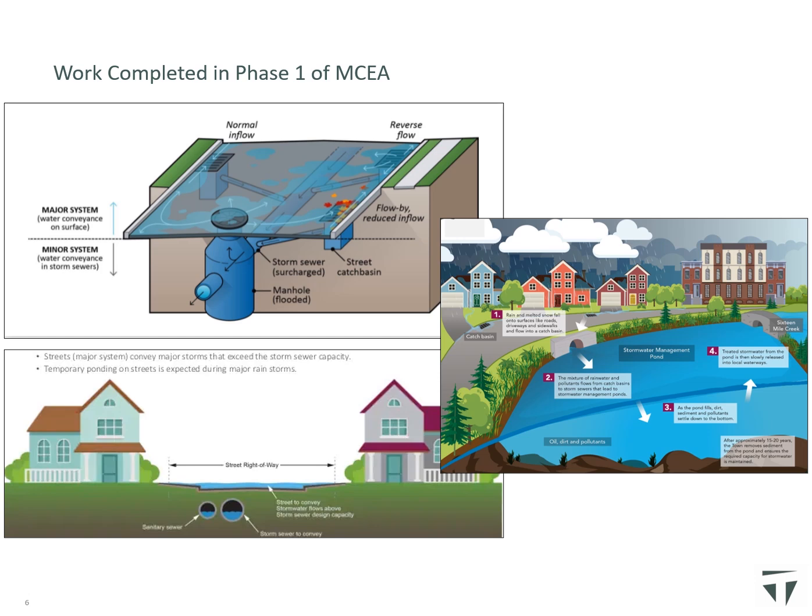The minor drainage system consists of catch basins, storm sewers, drainage swales, and roadside ditches which collect and convey runoff produced by frequently occurring storms, defined by the town in their engineering standards as a 1 in 5 year return frequency design storm, or the largest storm that's expected to occur in a given 5-year period.